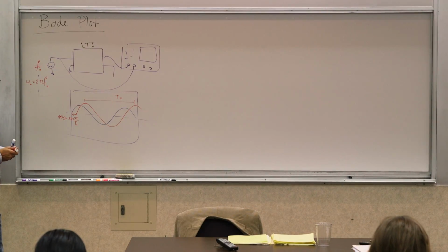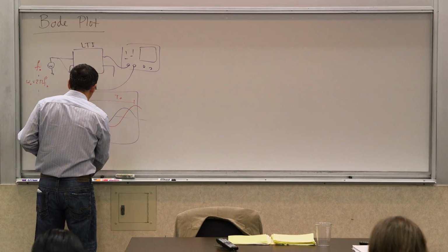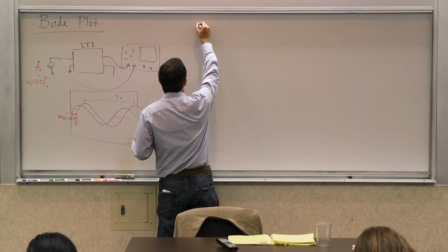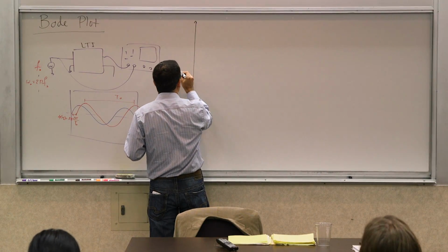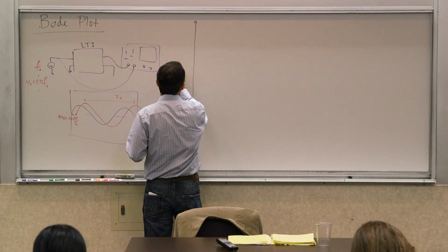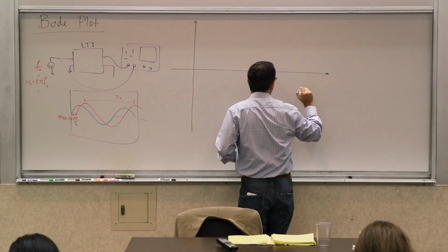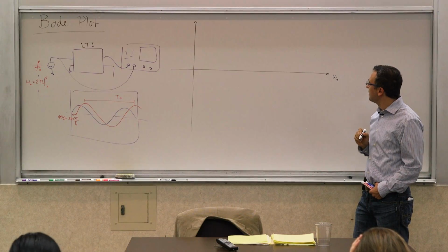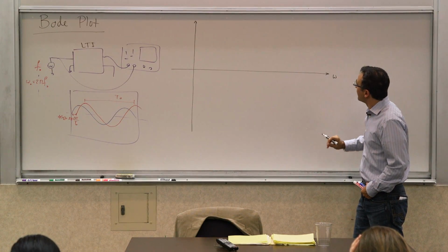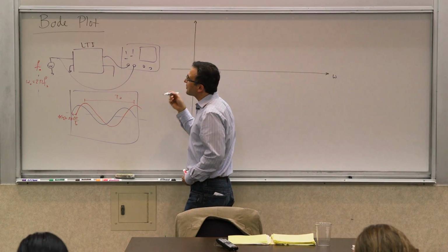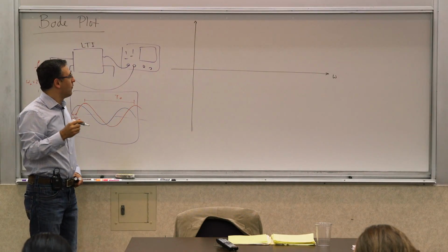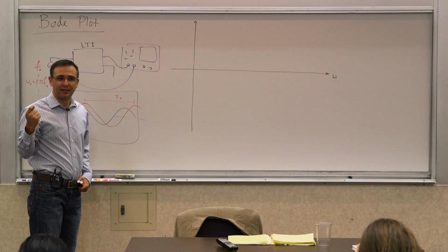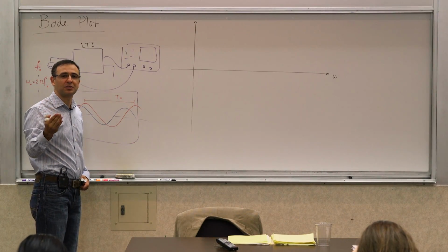Now, the Bode plot, we argued, is essentially a plot of these two quantities as you change the frequency. So it's nothing other than that. One of the significances that it has comes from the fact that it can be evaluated experimentally. So you can do it as a function of omega, and what you actually do is you measure it in dB. Now, what is dB? Or let's say measurement of dBs.